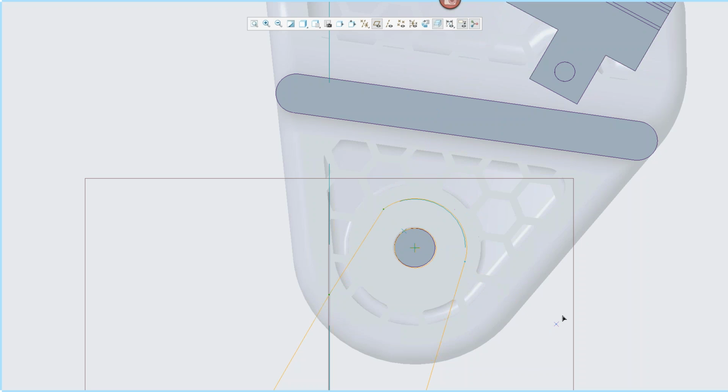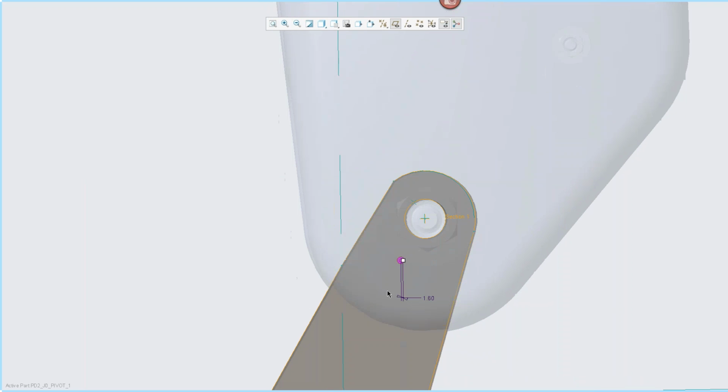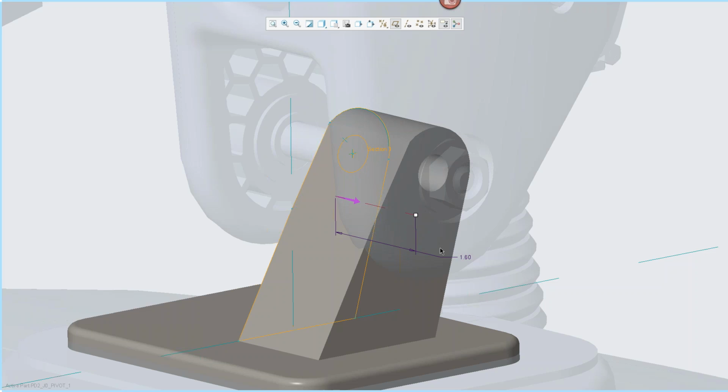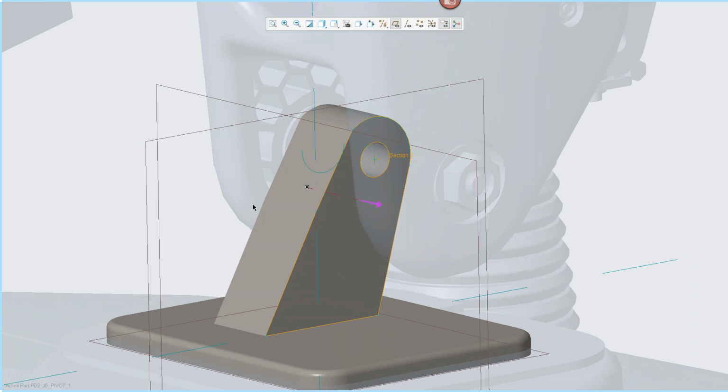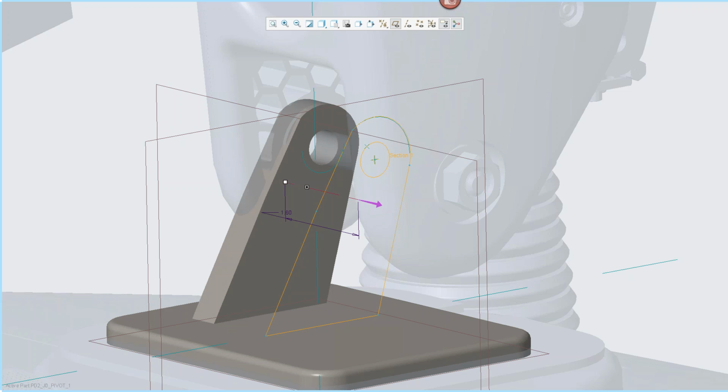Okay, now we're good. So I can accept the model from here just by using the right mouse button and saying accept. Now one of the really cool features in here as well, now we're in the extrude ribbon, I can hit select, grab this box, and then drag it to a certain face. So that makes my life a lot easier in terms of placement. Another really cool feature within Creo 4 is the ability to do a side to. Traditionally, you would create an extrude, and then if you wanted to do the side to, you'd actually have to create another extrude. It's not terribly difficult, but we made that more efficient for our users now.